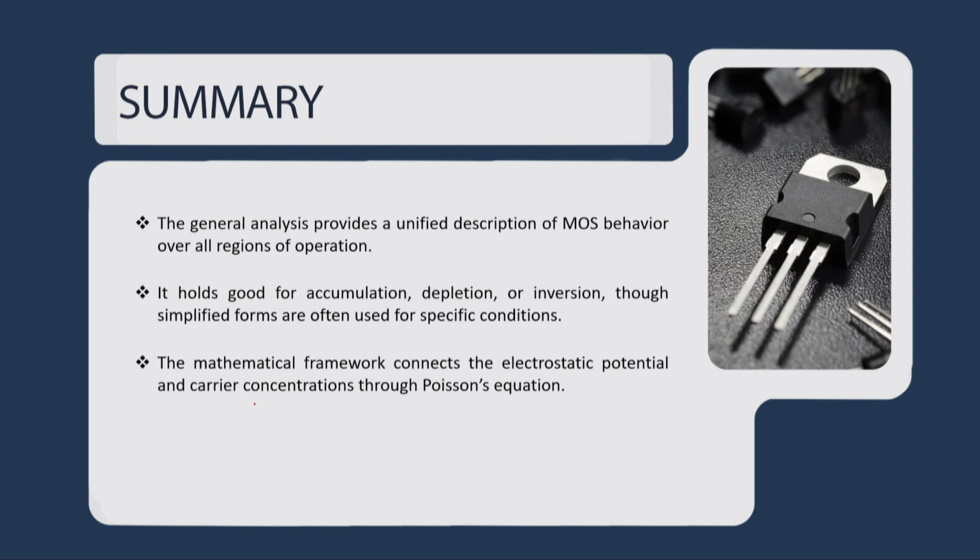So, let me summarize. We have discussed a general closed form equation or a unified model which relates the channel charge and surface potential in a two terminal MOS cap. We have seen that this expression holds good for all values of psi_s, whether my MOS capacitor is in accumulation, depletion or inversion. In the next lecture we will see how this relation can be plotted and interpreted in basic physical fundamentals, like what will happen when the surface potential is below flat band voltage and above flat band voltage, and how the charge responds.